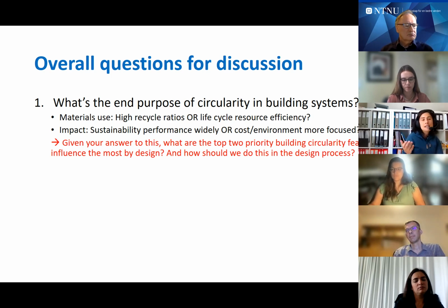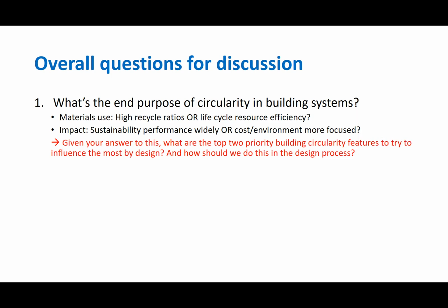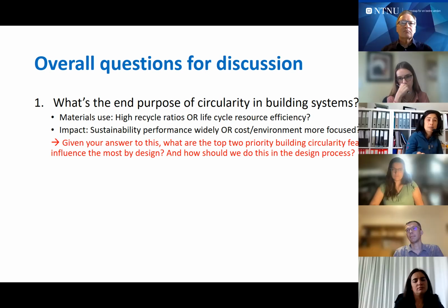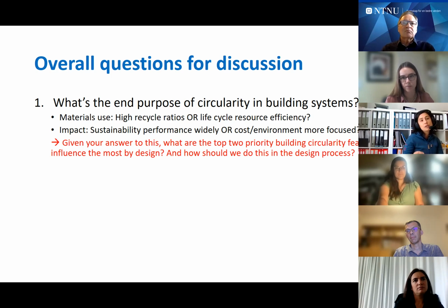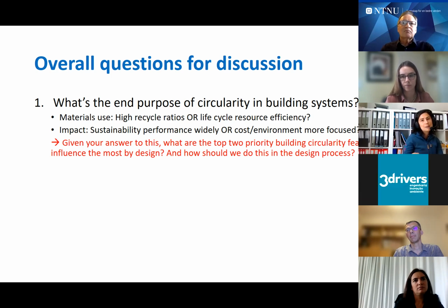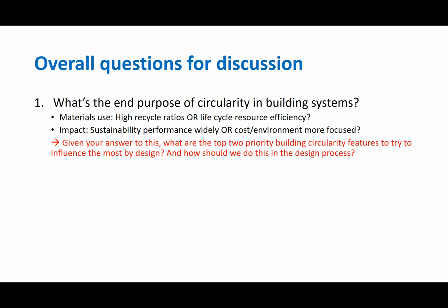on an early basis. And that could be a national effort, maybe for each country, or even a market effort, I don't know. And if you have impacts per square meter, then you could calculate the impacts of the buildings at an early stage. The simulation of energy needs is now much easier because you have energy models linked to the BIM model. It's not that hard to have the results of the energy needs and the end of life. Thanks a lot, Vanessa.